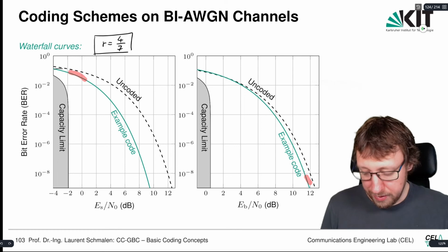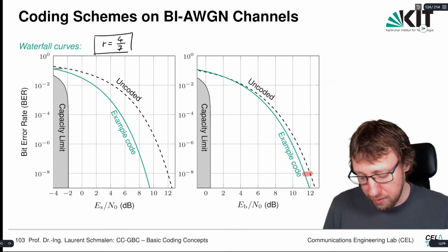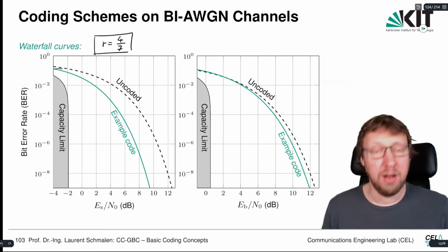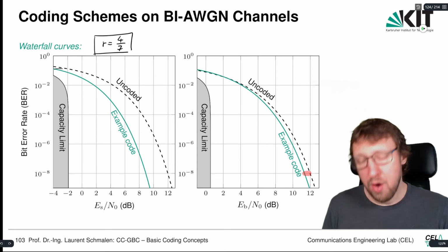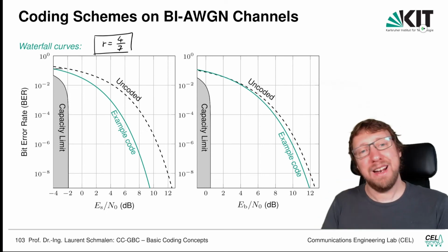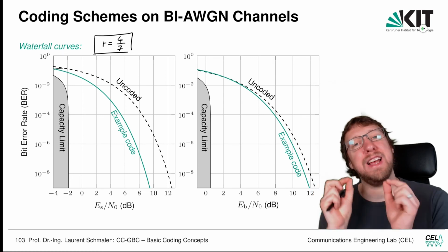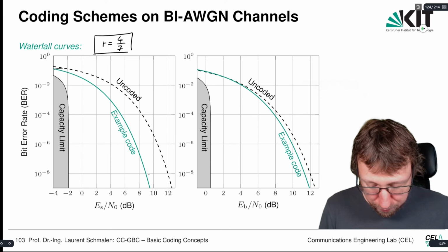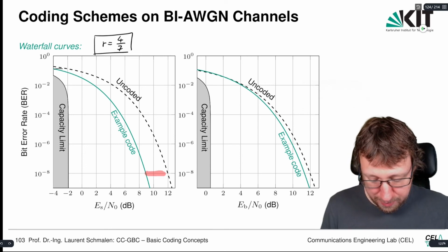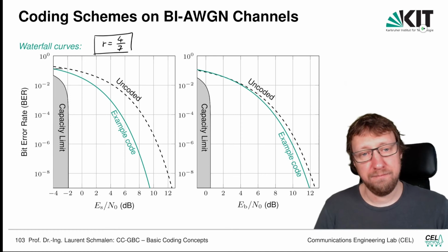And we saw that here the net coding gain is smaller than the coding gain. Recall, the net coding gain is when we look at EB over N0, where we need to spend energy to transmit the extra parity bits, so we can transmit less energy per information bit. And ES over N0 has a bigger gap. That's the gross coding gain.